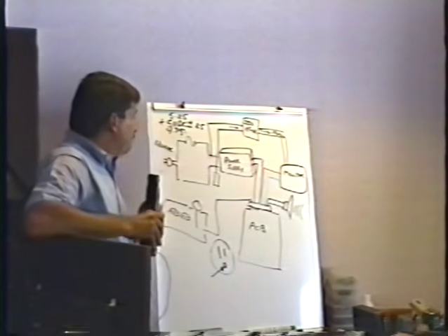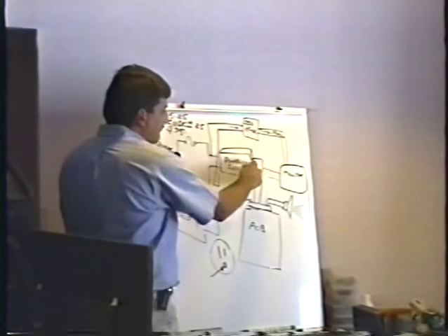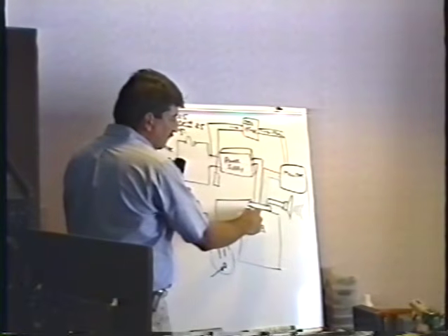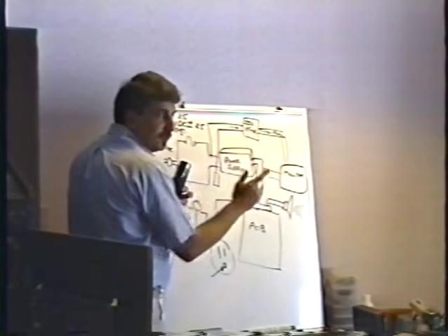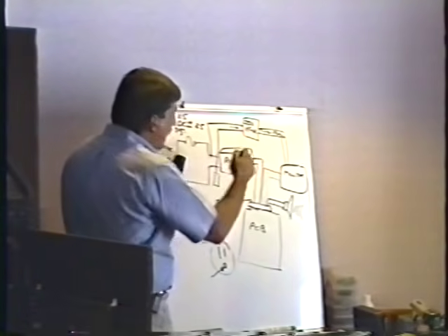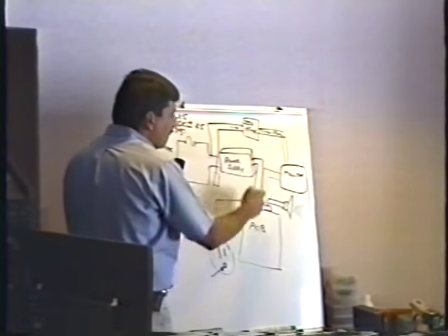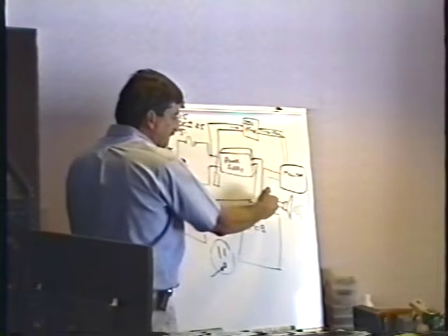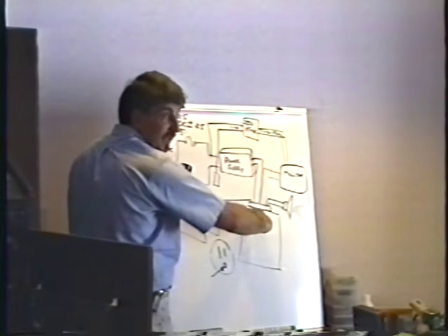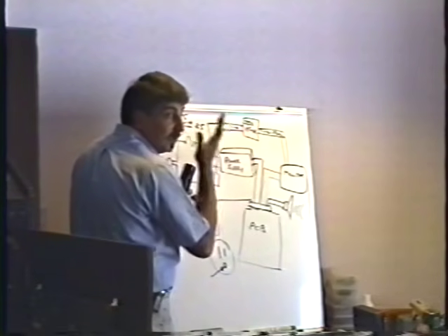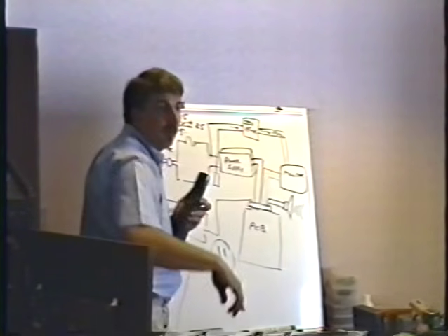You don't want to do that, because if you use this as a ground and just check the 5 volts here at the board, you're not checking this ground connection. In fact, I've screwed myself up that way. I've had a bad ground connection here. Using that as a ground, I checked it here, and I did have my 5 volts. But if I had gone right across from here to here, I would have seen that I didn't have my 5 volts. See, you're not checking that whole path that way.